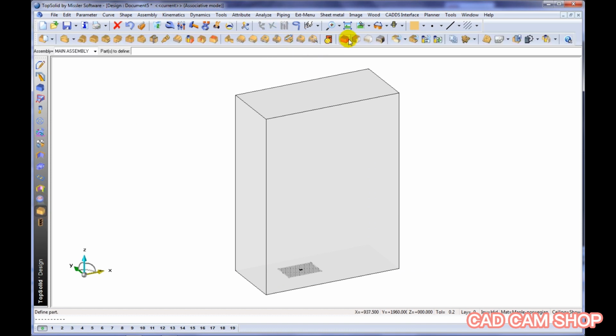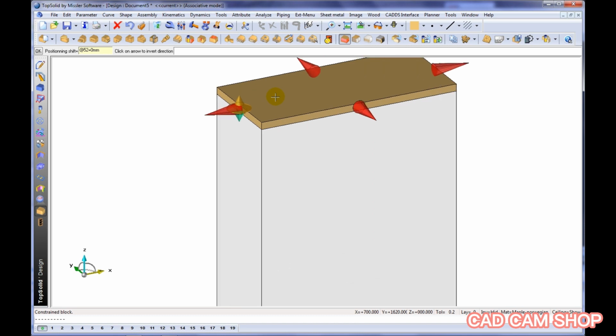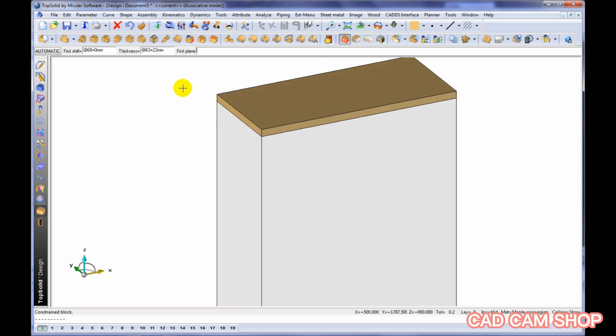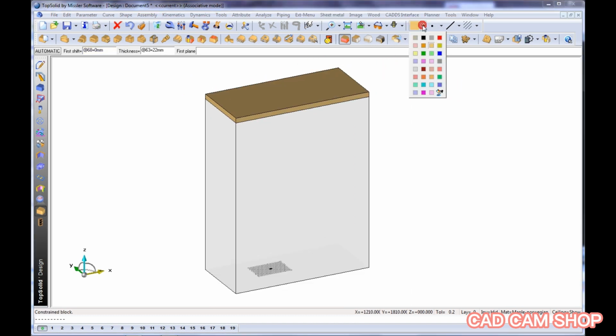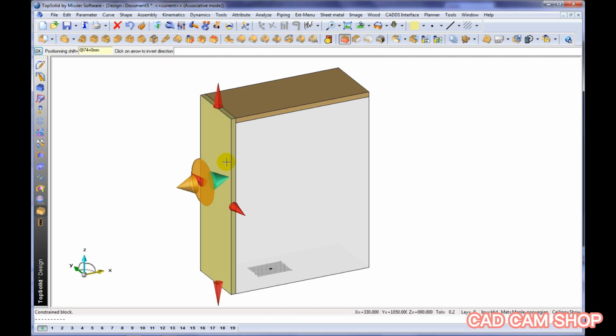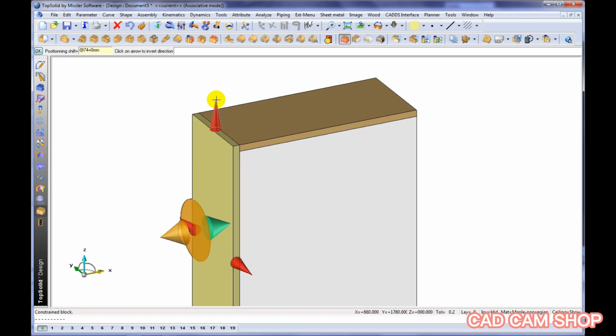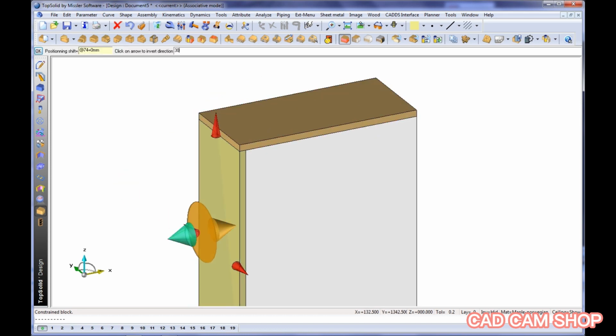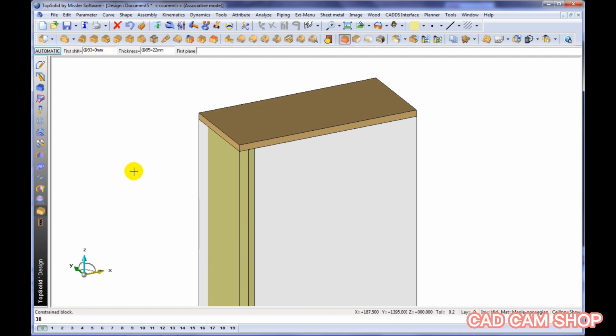Here's how. Here we're going to use a special function that allows us just to draw directly off of this volume. We can set the thickness of the board we want and validate, and like that we're done. Now this time we're going to take this and modify it to be hooked to that bottom face. We're going to flip that to be on the inside, plus give it a little bit of a shift. And now that piece is done.